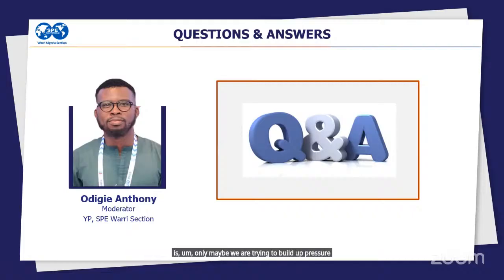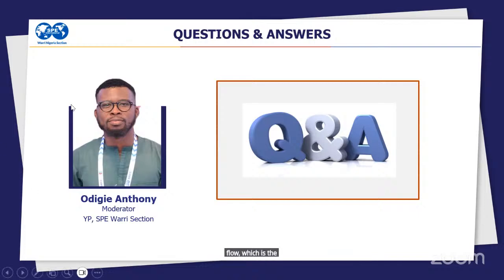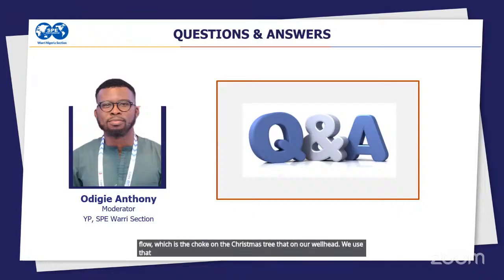So we shut the well for a period of time to carry out pressure buildup, allow pressure to come up, then we can resume production again. So there's no point at which it stops. Rather, what we do is regulate flow, which is the choke on the Christmas tree there on our wellhead. We use that choke to regulate the flow.